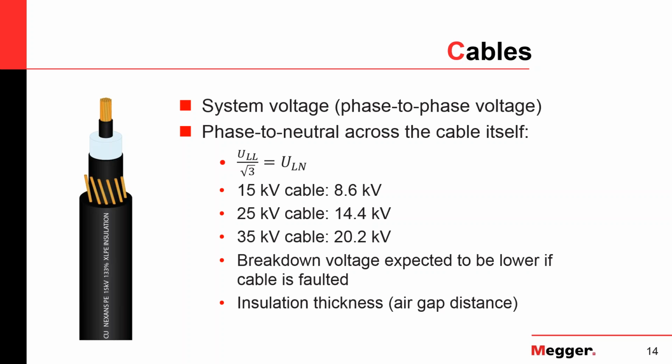Now, when you have a fault, and you apply voltage to the cable, you expect that this breakdown voltage, as we call it, is lower than the operating voltage, because whatever made the cable fail the night before, the day before, the week before, you expect this to be less, because it should have been good for the operating voltage.